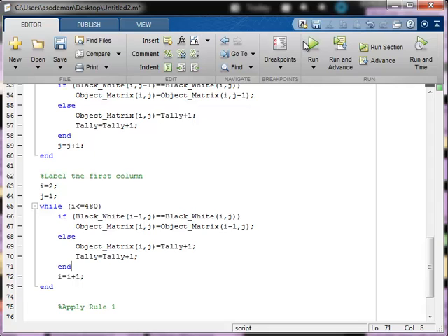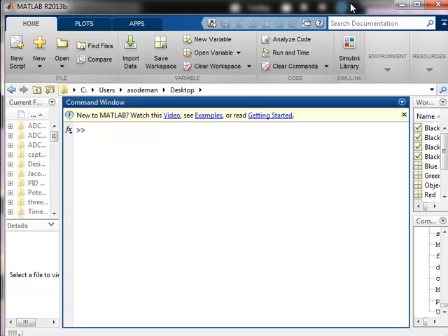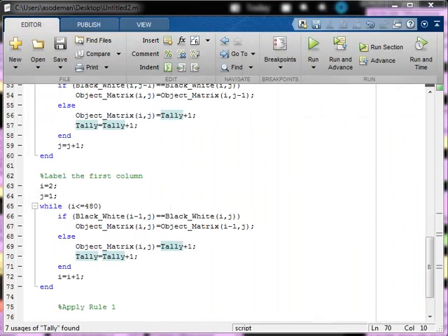Now we need to run this and check to make sure that we don't have any errors so far. Your output should be the same as before. You should have no errors in the Matlab command window, and you should have 4 figures open up: a live video feed, a still image that's in color, and then 2 images, one that's in grayscale and has 3 images stacked on top of each other, and a black and white image also with 3 images stacked on top of each other.